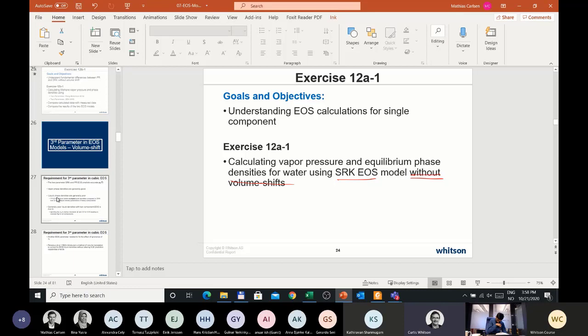The cubic equation just doesn't have the pressure volume dependency. It's cubic in volume; it needs to be different than cubic in volume to get the compressibilities right. So any single phase high pressure gas or liquid would suffer from this: you might get the right density at initial pressure, but you won't get the right compressibility at the initial pressure.